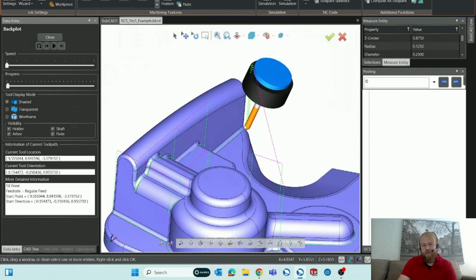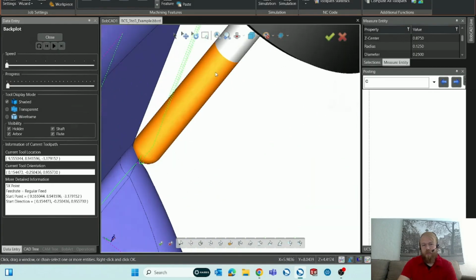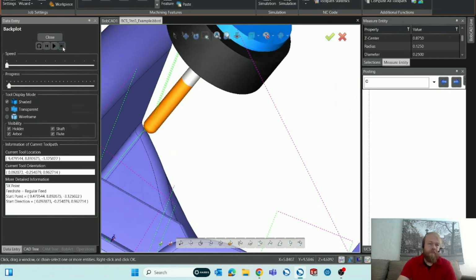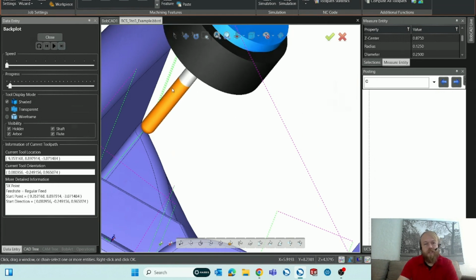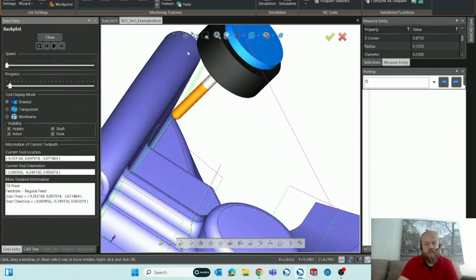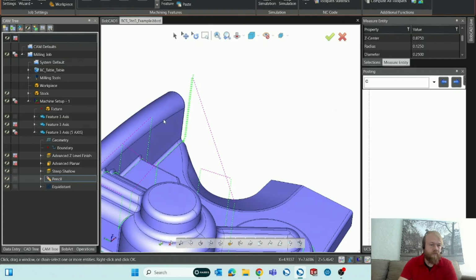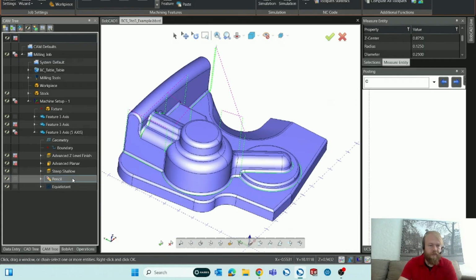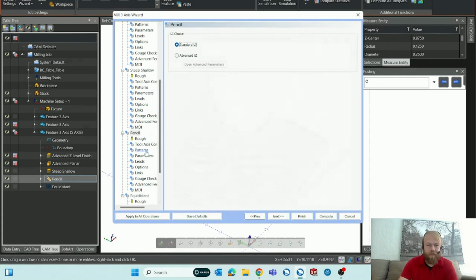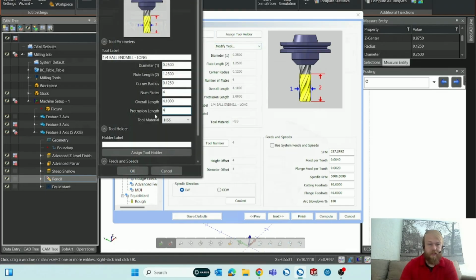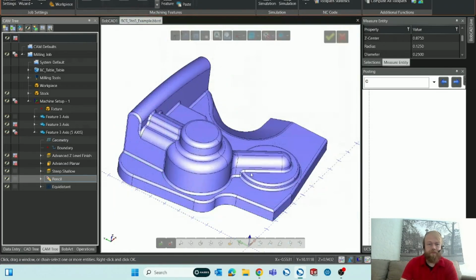The 3-axis milling operation will account for the tool, making sure that it doesn't gouge into the part, into the workpiece. But for the tool holder especially, it tilts the tool to make sure that it has enough clearance right here so that there's no gouging. So that's probably the best benefit I can think of for this gouge check page.